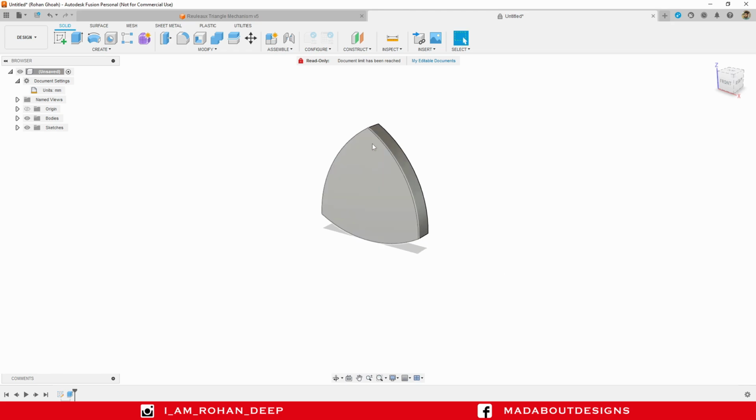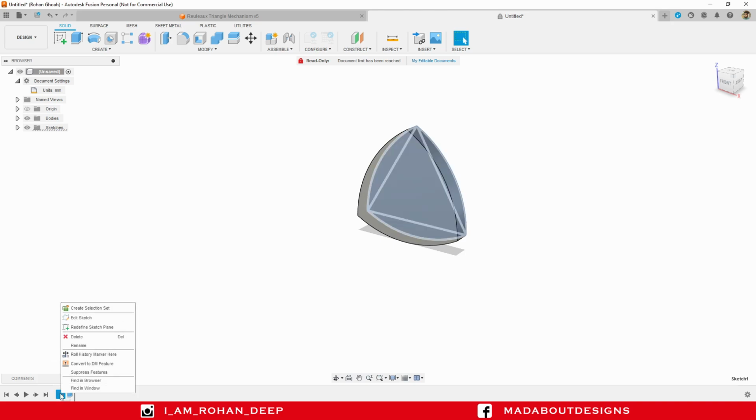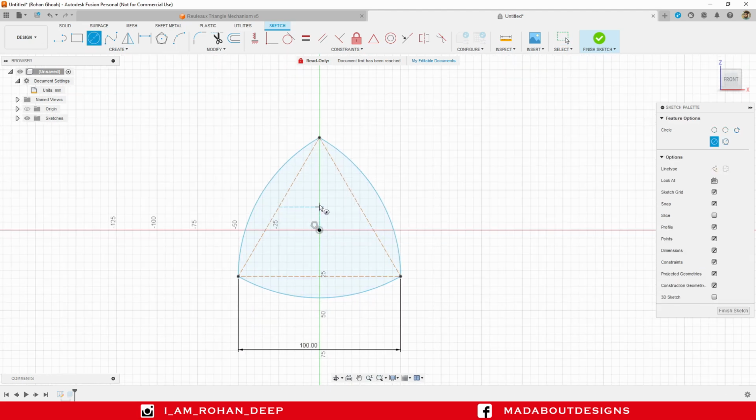I am going to create one hole on this part so that it can be pivoted to the base. In order to do so, go back to our previous sketch, right click and edit sketch. Press C to go to Center Diameter Circle. Select the center of the circle vertically aligned with the origin. Here, give it a diameter of 10 mm.